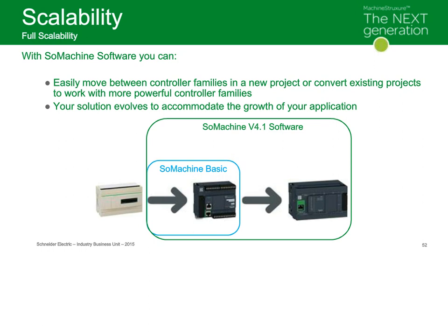With the Twido PLC, which some of you guys are familiar with, you're able to take your old TwidoSuite or TwidoSoft applications. You're able to open them with SoMachine Basic or SoMachine 4.1 software. But if you open it with SoMachine Basic, it'll automatically convert your old project file to a Modicon M221 PLC that most directly fits I/O configurations and stuff like that that were what you had before. Of course, you can then, within that software, change the controller. Even though the Modicon M221 is almost 5 times as fast as the Twido, it may not be enough horsepower for your architecture needs. No problem.